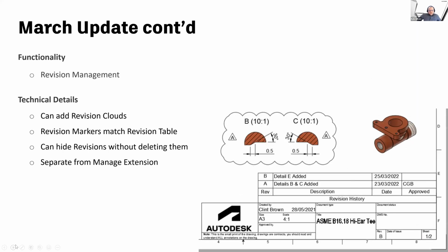And then next was the ability to add revisions. So this is the ability to have a new command that creates the revision table and then actually controls the revision process for you. Now, this is not part of a PDM system. This is actually separate from that. So this allows anyone that's using Fusion 360 to now create revisions a little easier. Before you could create this, but it would be through just a general table. Now you have a dialog box that pops up and has the ability to add revisions that way.